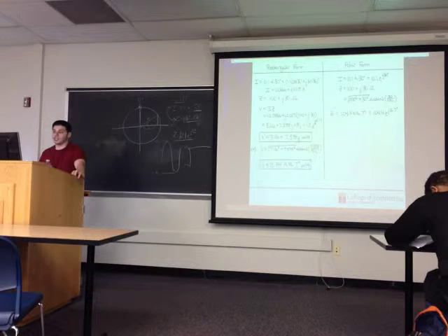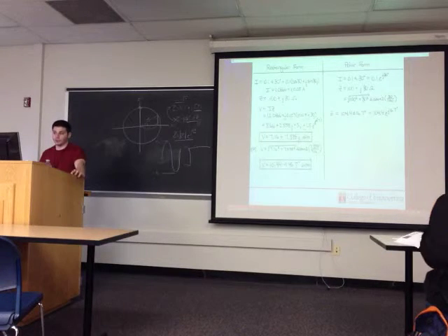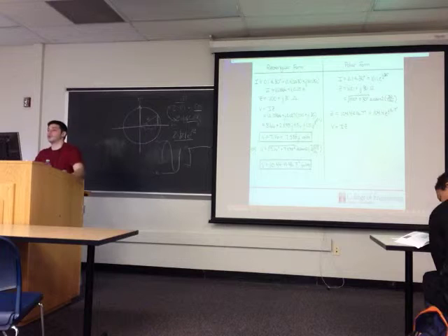Z is equal to the magnitude, the square root of these two quantities squared, which is 104.4, and the arctan of the imaginary, the 30, over the real, the 100, is 16.7. The exponential form is given right there. Now if we want to do V equals I times Z, our current times our impedance, what do you think we're going to do?